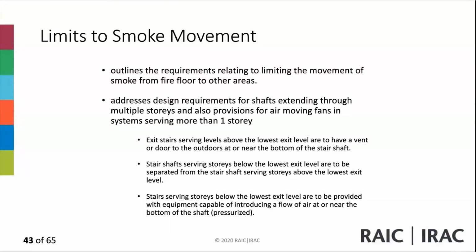And then stairs serving stories below the lowest exit levels are to be provided with equipment capable of introducing fresh air at or near the bottom of the shaft. So they need to be pressurized. You have to separate the stairs serving the lower levels from the stairs serving the upper levels, with a fire separation between them.